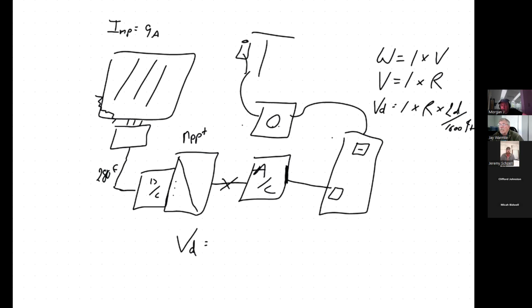Right, just the voltage is added. The voltage goes up. If the VMP on this was, let's say, 35 volts, then my voltage of that string is going to be 350 volts, but the amps are still going to be 9 amps. So I've got 9 amps for each string, but I've combined 3 strings in parallel right here in my combiner box. So what is the amperage for this particular wire here?